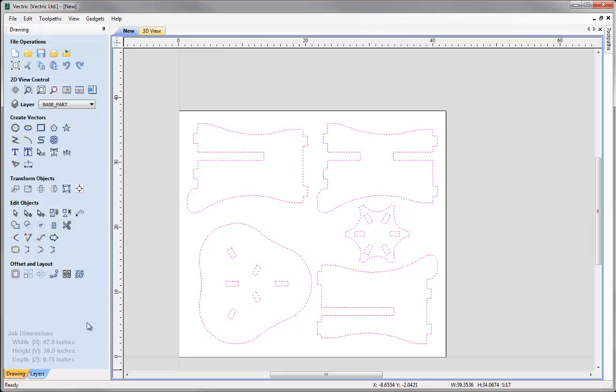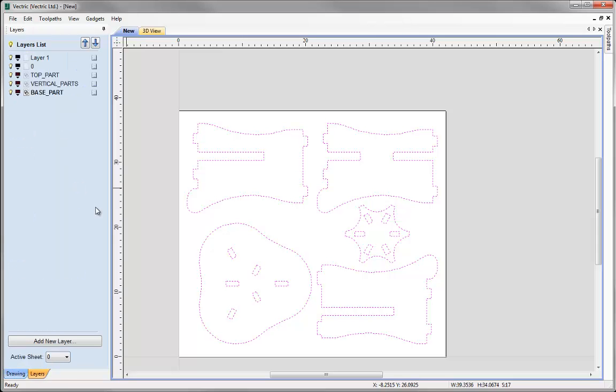As we have seen, importing vectors from a different CAD drawing program can also import the positional data that it was last saved with. With DXF and DWG files, you can also import any layer information that it was saved with. So we can take a look at this by going to the Layers tab down the bottom, and we can see that it has imported a few layers. Layer 1 was our default layer, and these other 4 are the layers that have been imported. Not all of these layers, however, have actual vectors on them, and we can tell that by looking at the third symbol along on each layer. If it doesn't contain the shapes on them, like these 3, it means that there are no vectors on that layer. We can tell this by coming over to the bulb and turning that layer off, and you'll notice that nothing disappears.